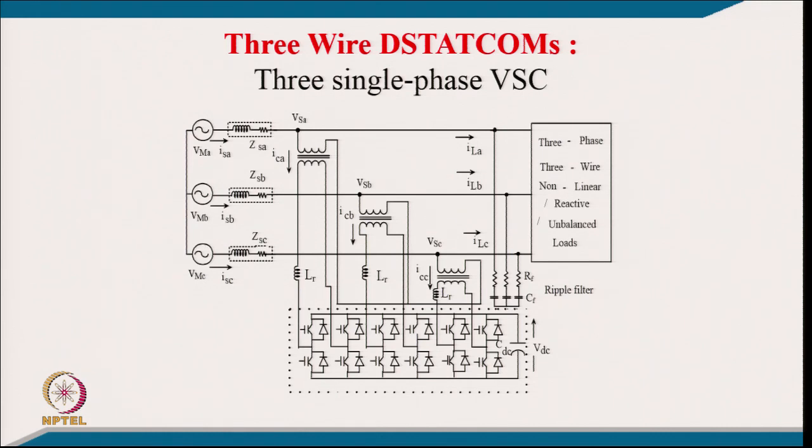Like in the previous first topology, if you are keeping 700, it can be only 400 volt. So, the device voltage rating also can be reduced, even when the transformer is used with unity turns ratio. The voltage rating of all the devices can be reduced, as well as the voltage rating of the capacitor.